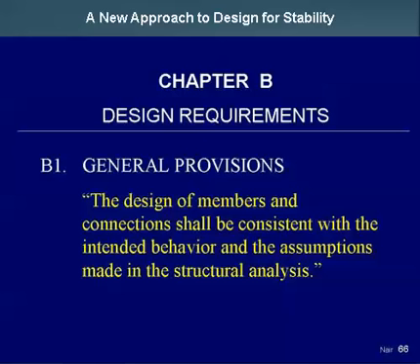Now, in some material, for instance in concrete, ACI goes into a great deal of detail about how to analyze your frame. They say things like use center-to-center distances of members, but then back off your moment to the face of the column and things like that.